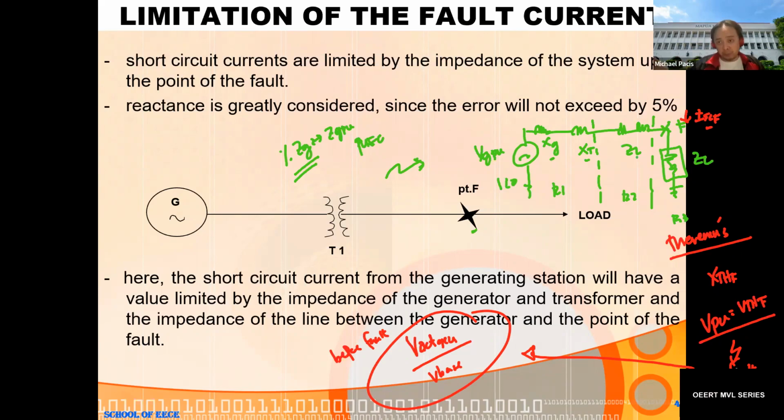The difference with post-fault is that post-fault analysis is where you want to do stability studies, reliability studies, frequency stability, voltage stability. Now, those are different things; you're considering transient behavior. But here, before the fault, you need to get the pre-fault voltage, and in order to do that, we have this formula here.